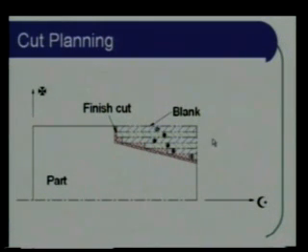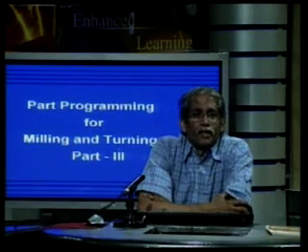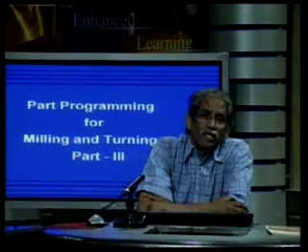So whenever you have arcs and inclined lines, it is a good habit to make roughing cuts, then a semi-finish cut, and follow that with a finish cut.